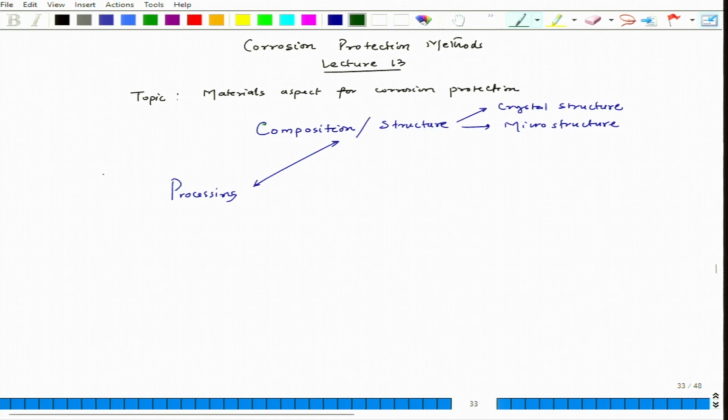Of course, here we are talking about heat treatment. So, heat treatment is a processing. Now, if we start with processing, the first thing to consider is casting. Because every material, first we have to melt, and then prepare the material, that means we have to reduce the ore and get to the metal condition. The most common process is the casting route, and in fact in the casting route we can also prepare the final product. Fine. So, this is a processing route which is casting.